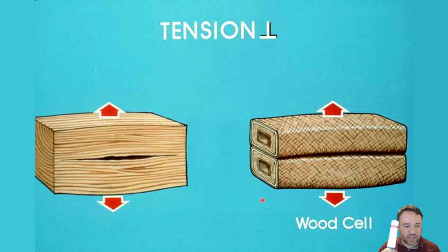So the cellulose fibers are quite strong. The lignin comparatively is quite weak. So it's good enough to hold it together to prevent buckling by making all the fibers act as one. But if I try to tear the straws apart from each other just by pulling them, it's comparatively easy because the lignin itself is not an extremely strong material.